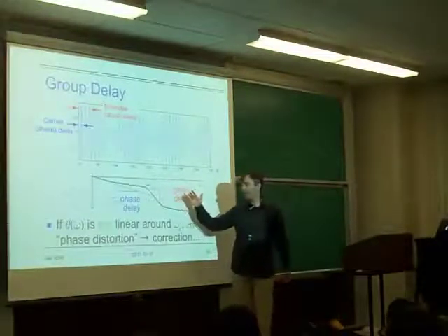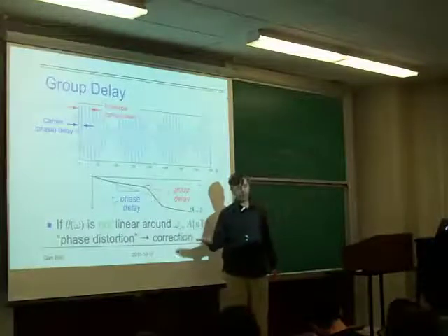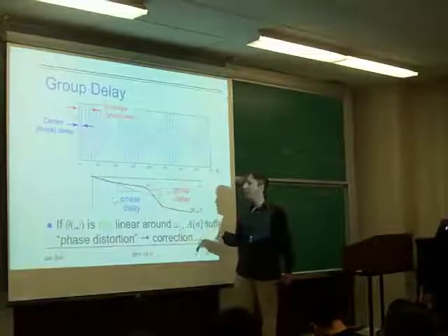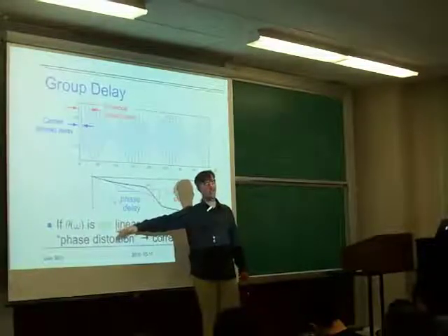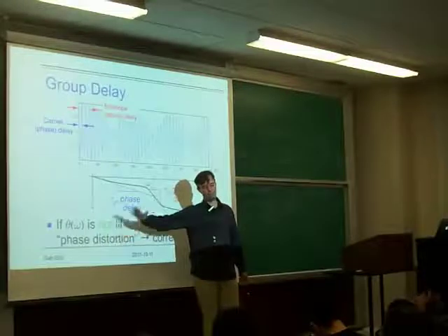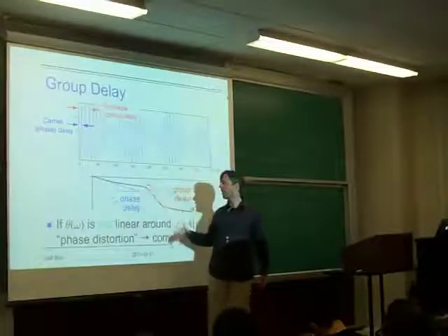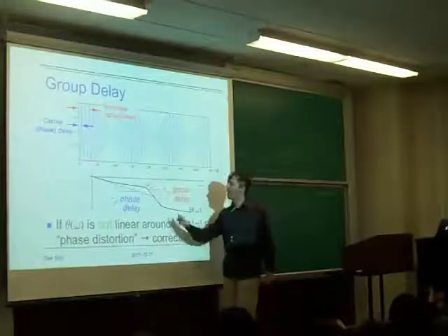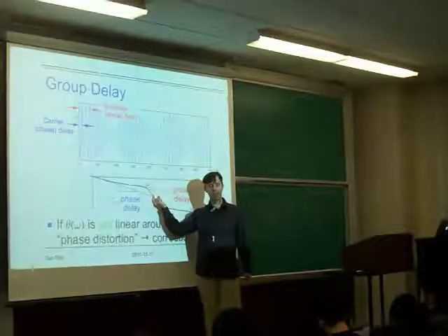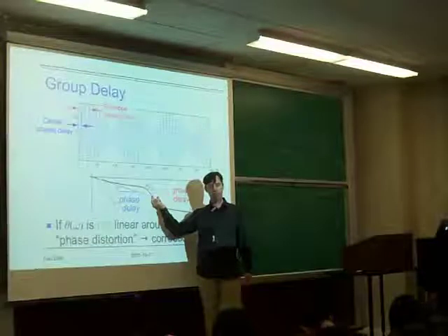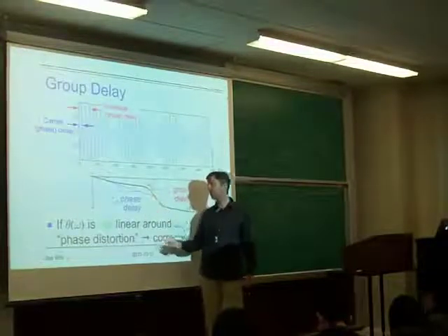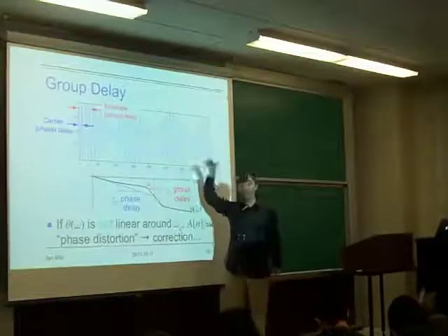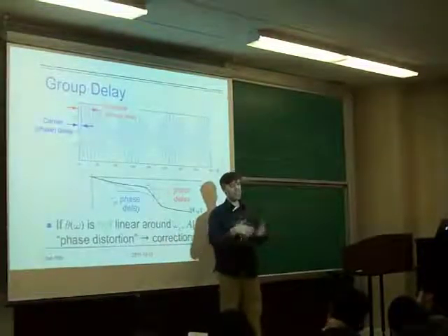To make this work, we made some assumptions, right? We assumed that the magnitude response was constant and unity, and we assumed that we were getting this nice first order fit, that we were approximating the phase function with a straight line. Typically, phase functions are relatively smooth, so if we have a narrow range of modulation frequencies, then this is going to hold. And this was for one sinusoid, but of course we could have decomposed the envelope into multiple sinusoids, and it still would have worked, right?